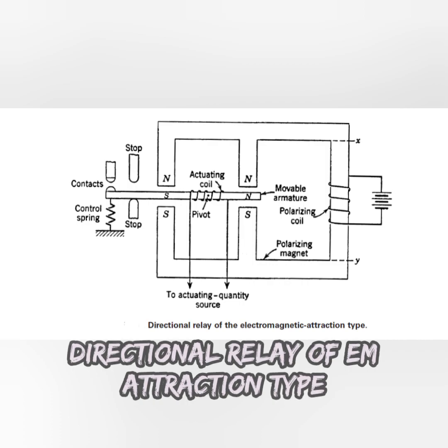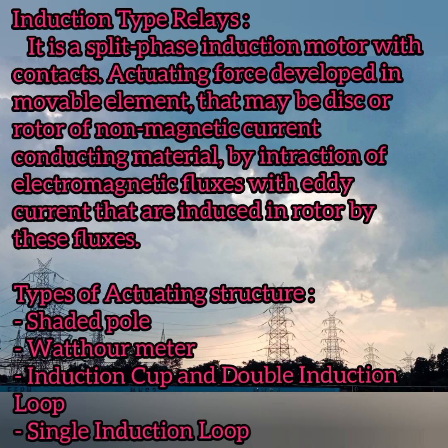Next, coming up to the induction type. The induction type relay is like a split phase induction motor with contacts. The actuating force is developed in a movable element, that may be a disc or a rotor, of non-magnetic current conducting material. It is carried out by the interaction of electromagnetic fluxes with the eddy currents that are induced in the rotor by these fluxes.